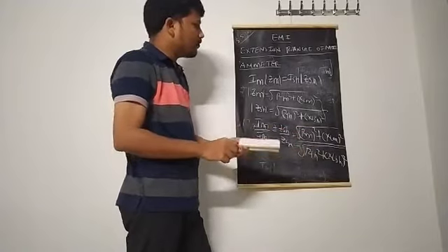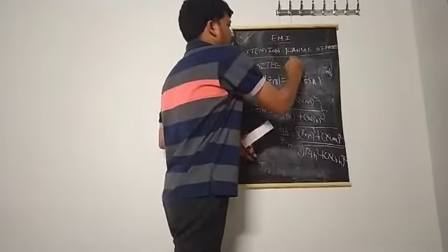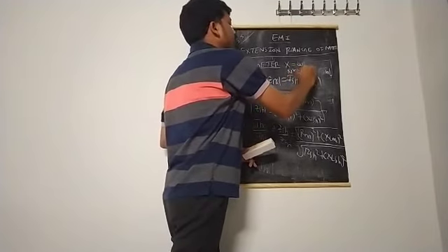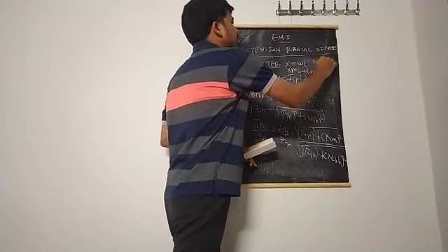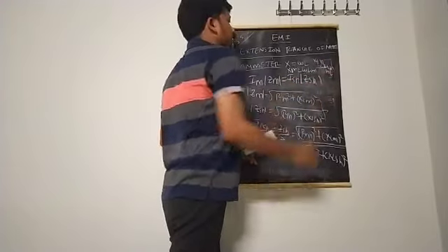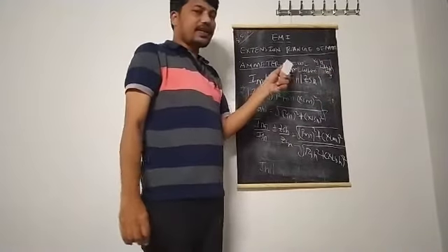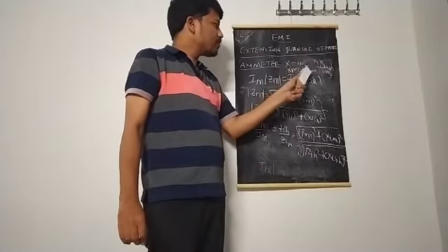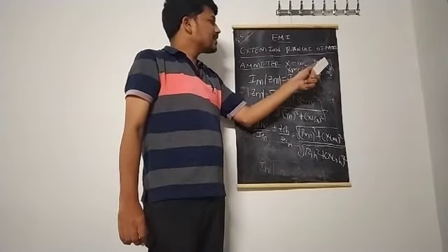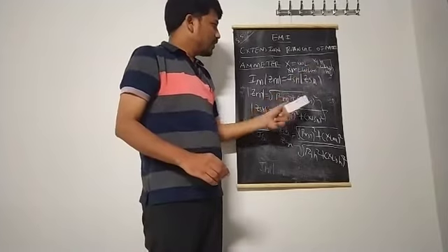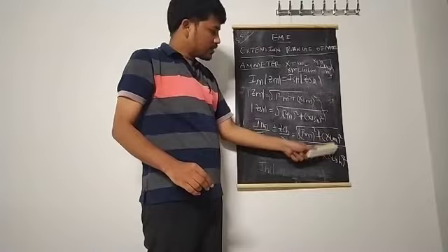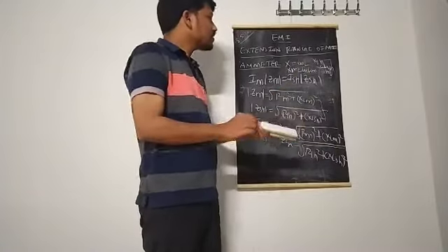We know that X is reactance. Reactance can be written as omega L. Similarly, Xm is omega Lm, and similarly XSH is omega LSH. Is it clear? So X is nothing but reactance, that is omega into L, where omega is nothing but 2 pi f. Xm is omega Lm, XSH is omega LSH. Let us substitute the Xm and XSH values in this equation.